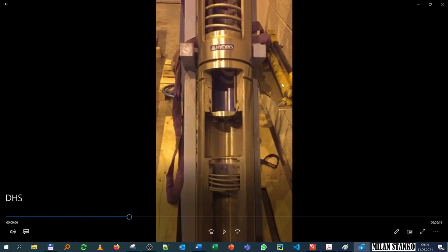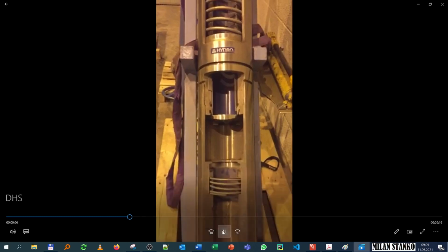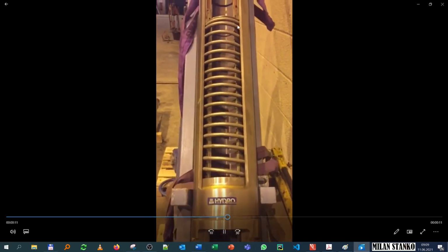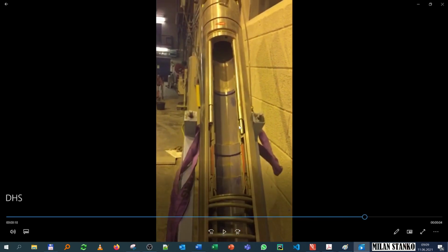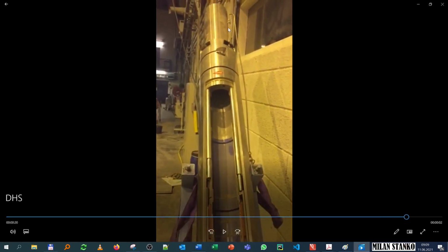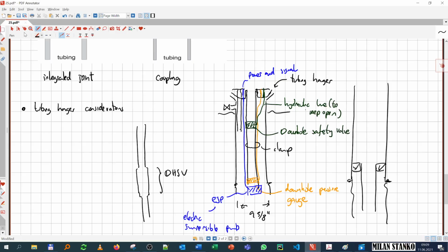You're going to see now very quickly an animation of this. And then you have that spring which is holding here and pushing this one up, so it's pushing this inner pipe up. And here are the cylinders that are activated. These get hydraulic fluid from the surface, and these are pushing to counteract the spring. And maybe up here, you see these capillary tubes, the hydraulic line, that we specified here on our drawing. It will be this green one here.